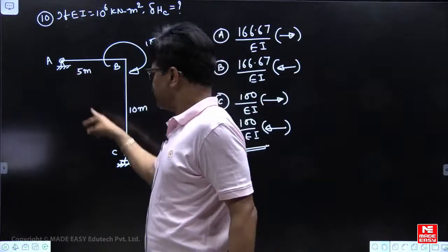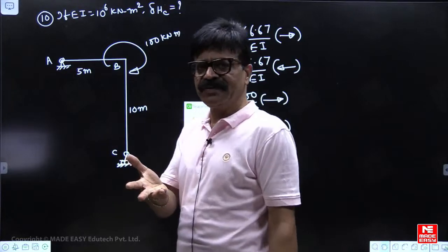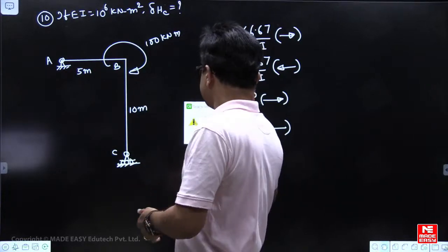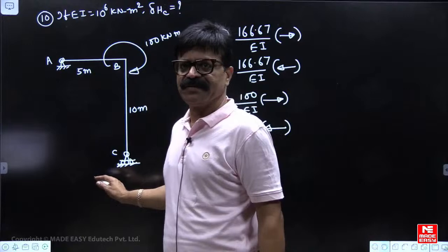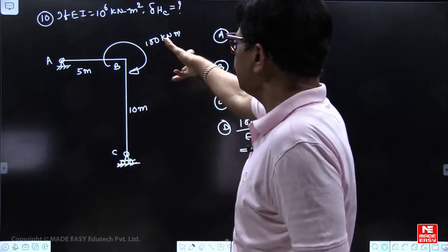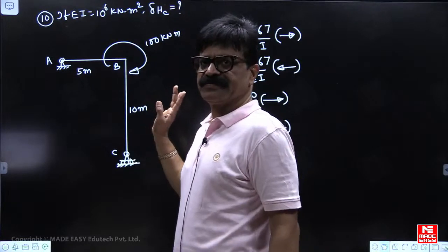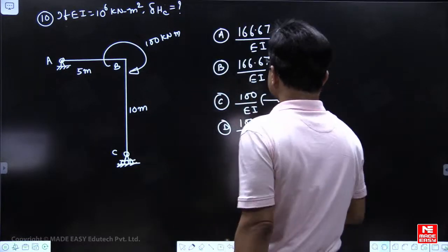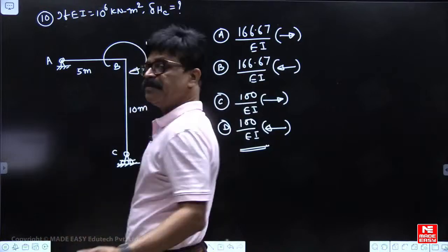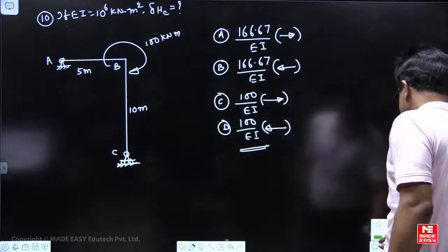So instead of applying a point load at C always, that question all of you know. Now it is not necessary that they must give load at C only. Suppose a moment is given, say 100 kilonewton meter moment is applied. What is the horizontal displacement of joint C? Okay, so these are the options. 1 minute time, quickly try if you can manage this one.